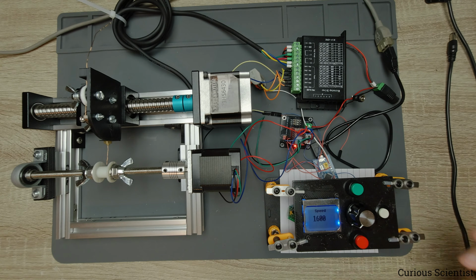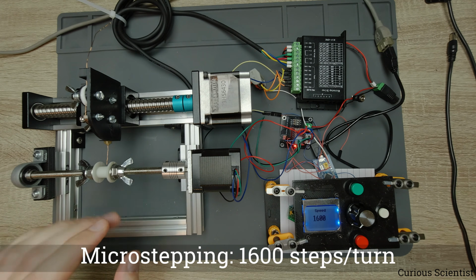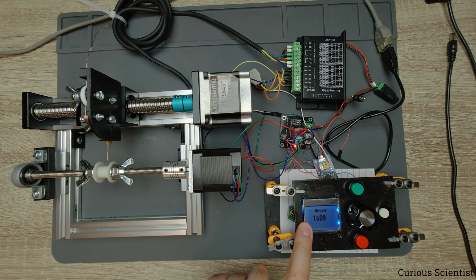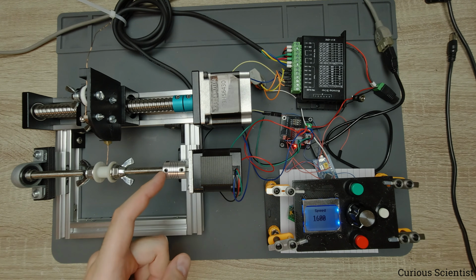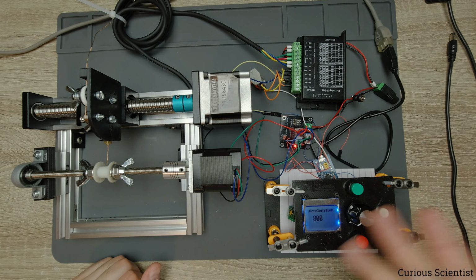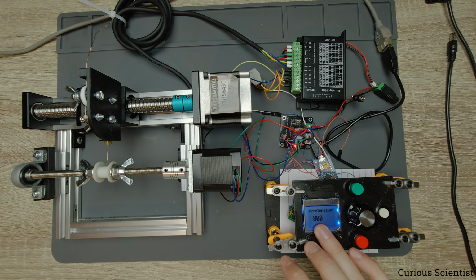Then we have the welcome screen, and then we can set up the speed, which is steps per second. And now I'm using both motors with 1600 steps per turn microstepping. And in this shaft, this 1.6 means that one turn will be done on the shaft per second. And that also means that this speed is now 60 RPM, so 60 revolutions per minute. And then acceleration, in fact, I removed that feature. Everything is quite low speed, so we do not need accelerations. So this is not relevant right now.